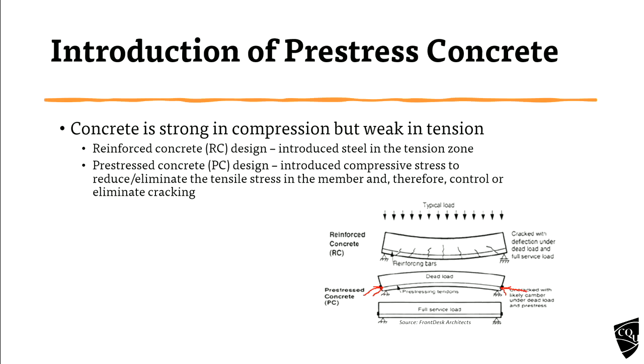Now we don't have any loading, so we are constructing the beams. When you apply some compressive force in a beam without any loads, only dead load or self weight of the beam, since you apply the compressive force below the neutral axis, the beam will bend upward.